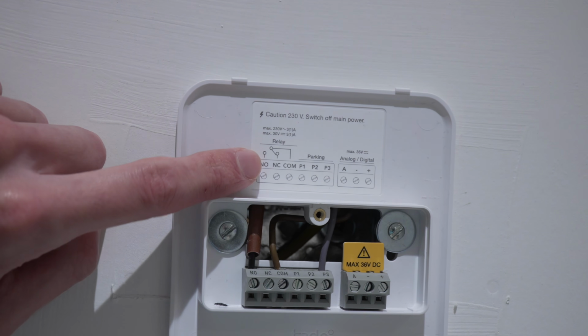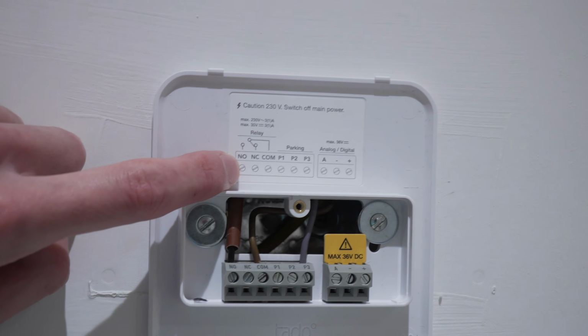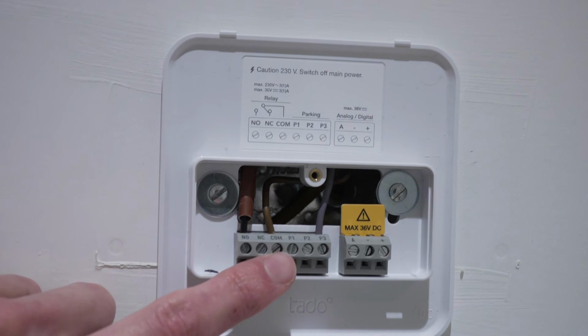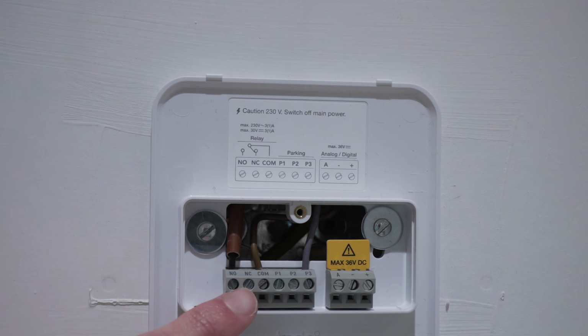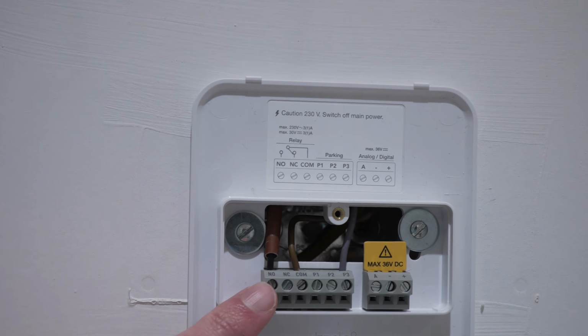and then as we can see up here, a very similar sort of setup to the diagram we saw on the Wiser. The common is connected through the relay to the normally open contact. When the heating turns on, this switches across and connects common to the normally open terminal. So we have our common is a permanent live, that's a permanent 230 volt live. And then when the heating turns on, that gets connected through to normally open. So the brown and black wires essentially get connected together, and that turns the heating on for this zone.